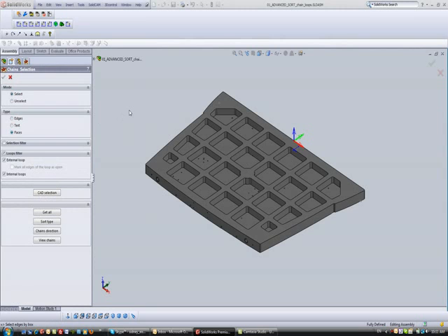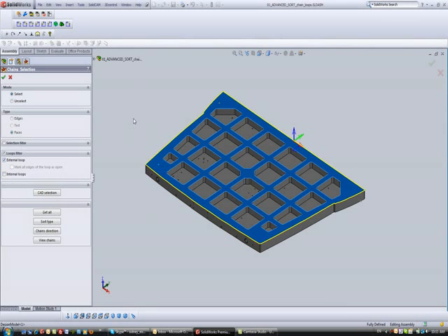Now when I choose the option of faces, we have here the option of choosing either external loops or internal loops, or both. If I choose to work with only external loops, when I touch the surface, I will only get the outside chain. It will ignore everything that's inside that boundary itself. Doing unselect will unselect that boundary.